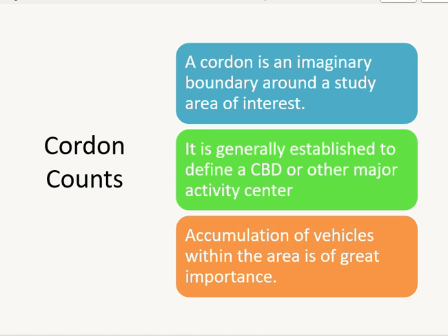Since I'm making the boundary, I have to keep a few things in my mind, because it's my choice, right? How much area I will put under the boundary, it's my choice. First of all, the most important concern is the size. How much should be the area within your cordon, within your boundary? You can go to two extremes. You can make it very small. It will be easier to manage, right? A small area will have fewer streets and intersections, fewer crossing points, easier to manage.